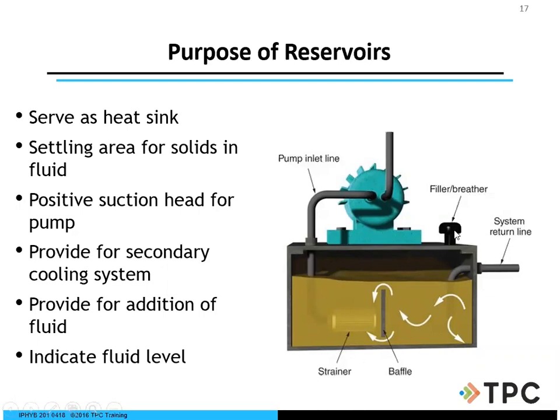A breather, critically important. If our reservoir is not properly breathing, then it could heat up on the inside. If other contaminants from our environment get into our fluid, that's not a good thing. A lot of manufacturers put desiccants of some sort on top of our reservoirs to keep the air going into the system nice and clean. Our pump inlet line is over here. So we have the suction, then we have the discharge throughout our system over here.